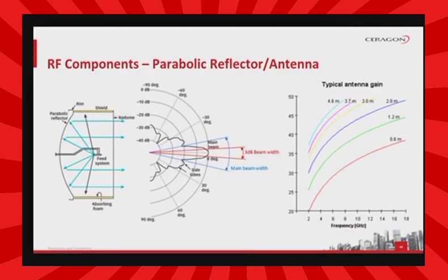Microwaves travel in straight lines and they can be focused and reflected just as light rays can be. A feeder receives the microwaves from the waveguide and then transmits them through a parabolic dish's reflecting surface to the other side of the link. The wavefront reaches the reflecting surface of the antenna, and then it leaves the antenna in parallel paths. Because of the special shape of a parabolic surface, all paths from source to the reflector and back to the end user are the same length.